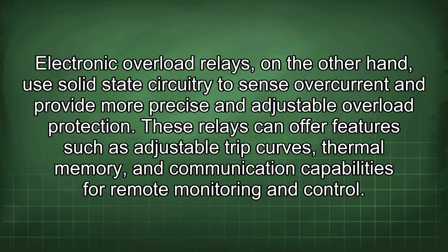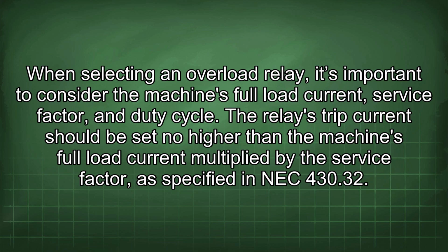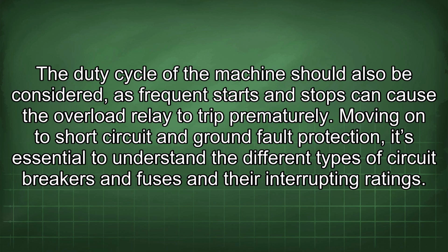protection. Electronic overload relays, on the other hand, use solid-state circuitry to sense overcurrent and provide more precise and adjustable overload protection. These relays can offer features such as adjustable trip curves, thermal memory, and communication capabilities for remote monitoring and control. When selecting an overload relay, it's important to consider the machine's full load current, service factor, and duty cycle. The relay's trip current should be set no higher than the machine's full load current multiplied by the service factor, as specified in NEC